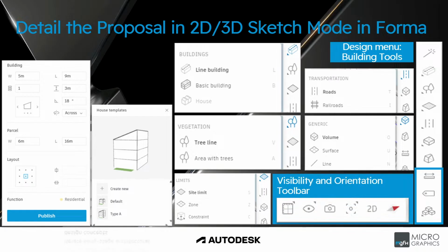Then you have control over your visibility and orientation toolbar. In the lower right corner in Forma, you can access the following tools. You can check on and off snapping for your elevation above sea level at cursor. Toggle between terrain map, texture, contour lines, and satellite imagery. Save a camera position and load a pre-saved position. Look from a point or zoom to fit the entire proposal in the view. You can switch between 3D and 2D view, and you can also orientate to true north orientation.